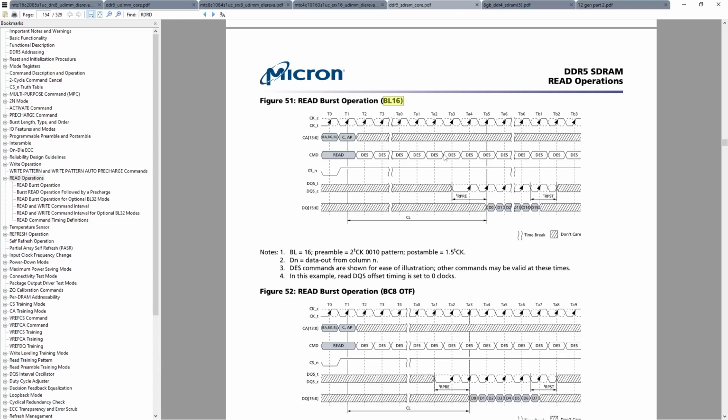One of the reasons why Intel had this not really dual channel configuration for so long is that it actually has latency benefits. It has slightly lower latency if you're only trying to access 1 byte of data. I am not entirely certain why. And funnily enough, there are certain DDR3 platforms where you could toggle between true dual channel functionality and an overgrown single channel. It's not an option on DDR4. As far as I know, Ryzen has always been true dual channel. The HEDT platforms from Intel were always true quad channel, and Intel mainstream until Alder Lake was giant single channel, as far as I know.